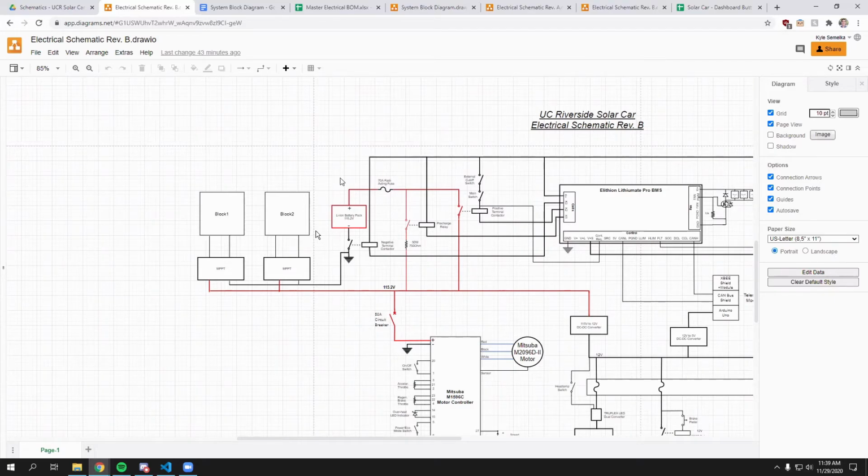So say we have a sheet of like 18 PV cells. With a center tap, we can put 2 bypass diodes on that sheet, so 1 for every 9 cells. But without that center tap, we would only be able to put 1 per every 18 cells. So that's the benefit of having those center taps.